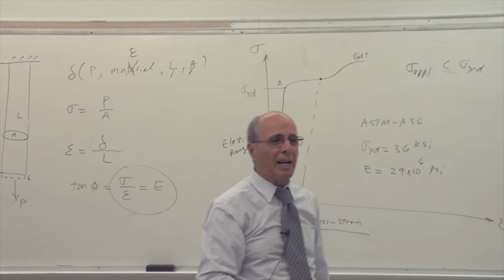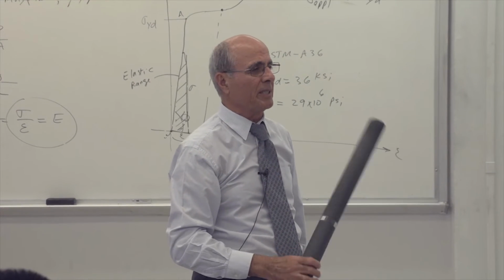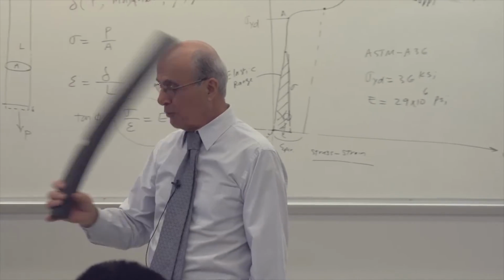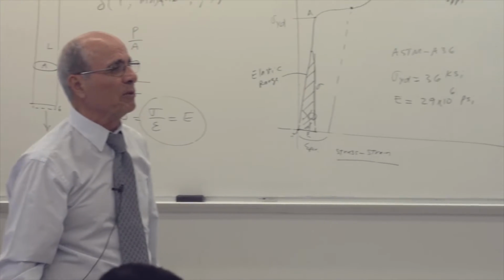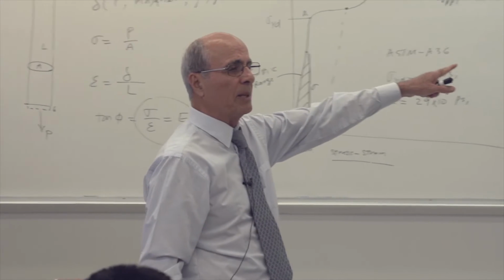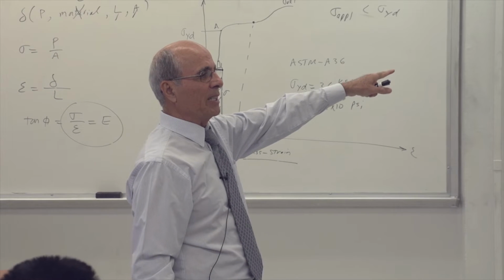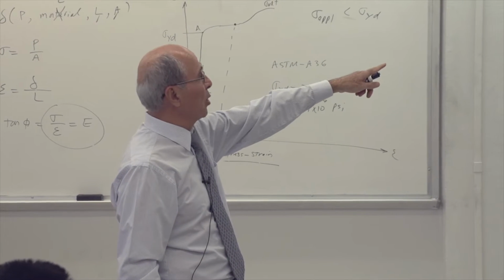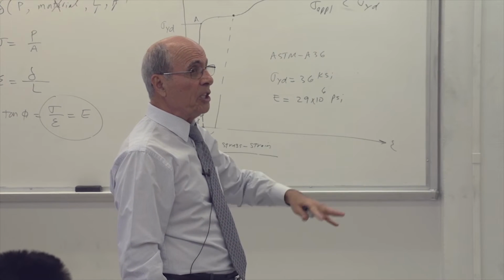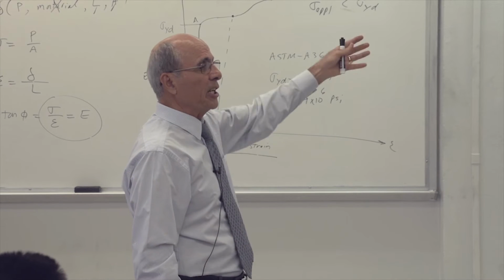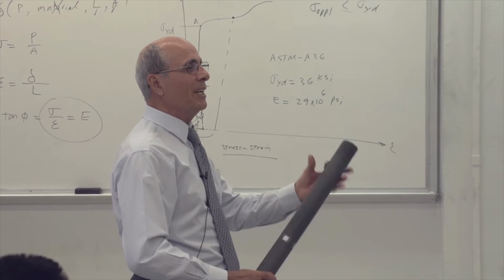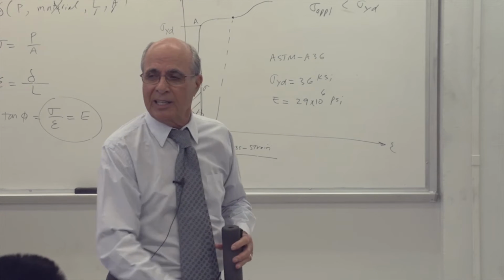You may remember it today, and if you don't use it for a few weeks, you may forget it. Yes, I said you never forget it, because at least as long as you are in ME 218, you are not going to forget it. If you're going to become an engineer, you will never forget it. Everybody understand that. But look whether the same concept is applied there. Look at the more P you have, the more delta. Everybody see that? P becomes larger, delta becomes larger. The more L you have, the more. However, if the material is stronger, E is larger, yes or no? You get E larger, delta becomes smaller. So it's reverse, it depends on the modulus of it. Also the area, the larger the area, the less delta.